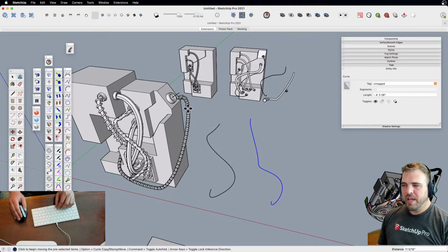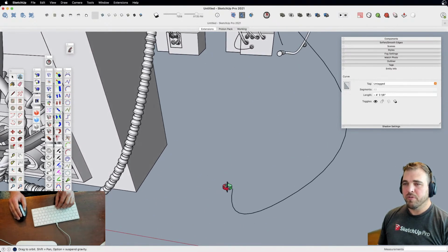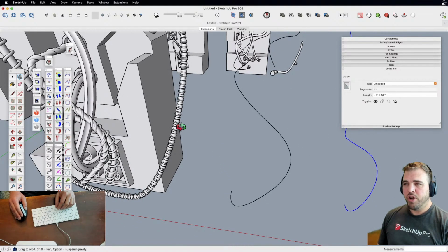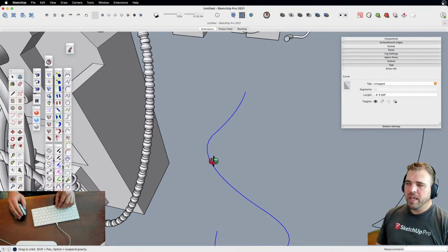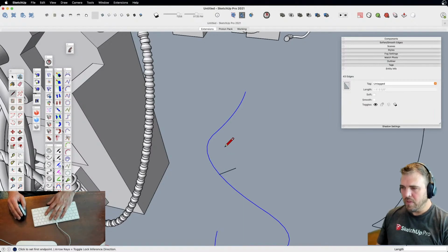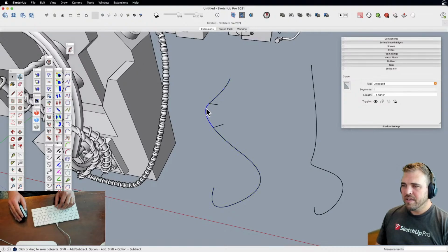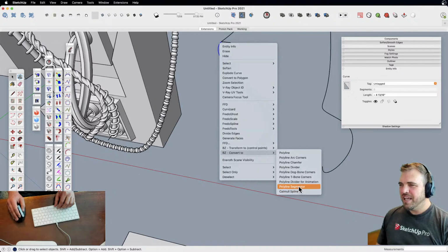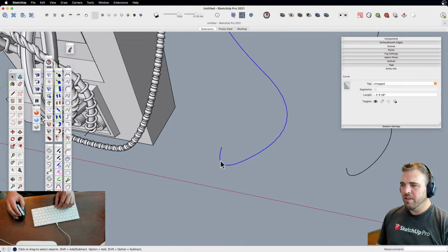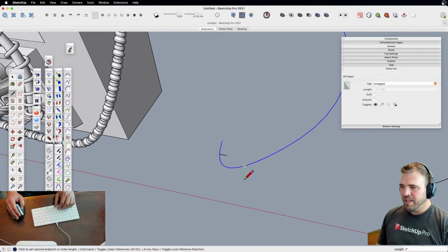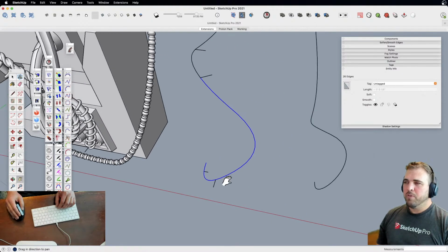Let's do this same idea, but show different tools. That one, like I said, was Chris Fulmer's component stringer. It's free, and the key with it is that it's going to put a component at each segment. So you need to change the number of segments if you really want even distribution. And what you may do, again, for curves, is isolate this part, move this way up because it's at the bottom down here, and say for this one, let's say 12 segments, and then do the same down here where I increase the number of segments in a tighter curve than in the general curve. So play around with doing stuff like that.